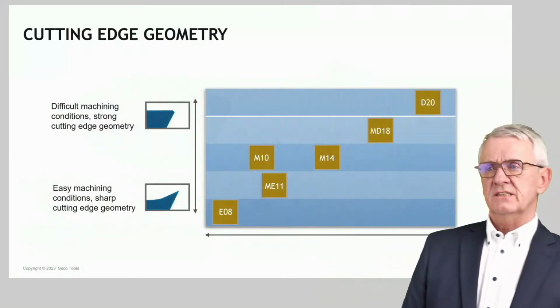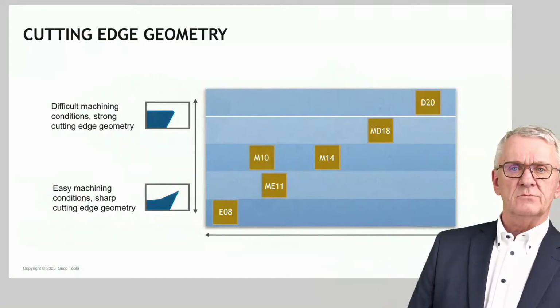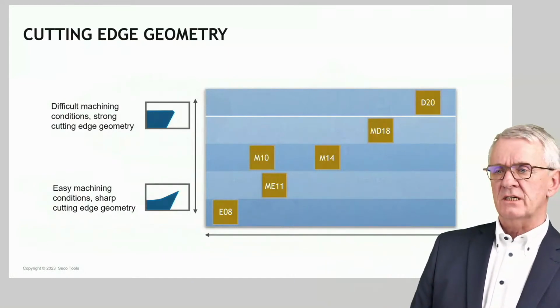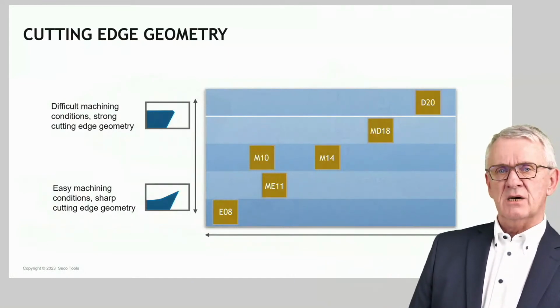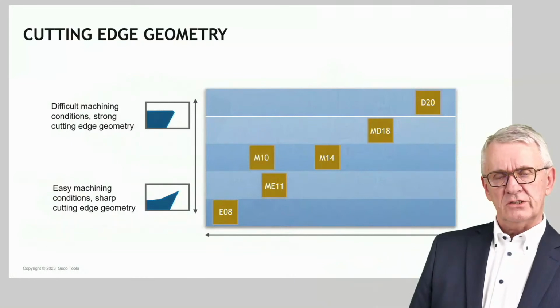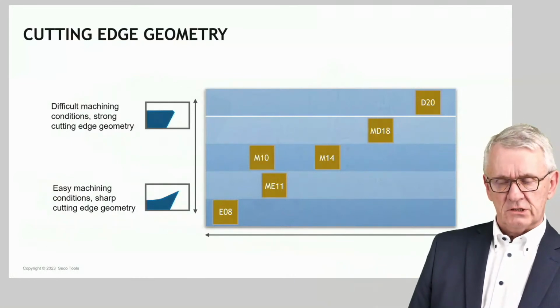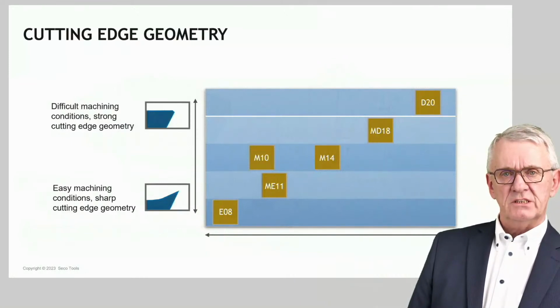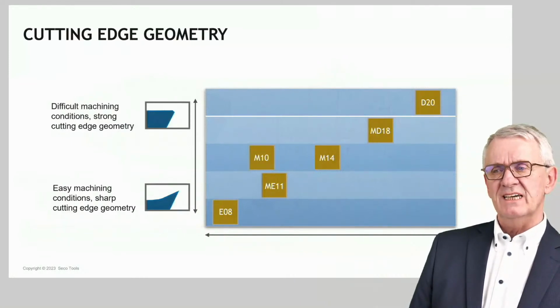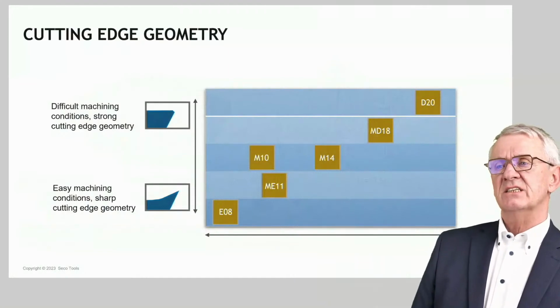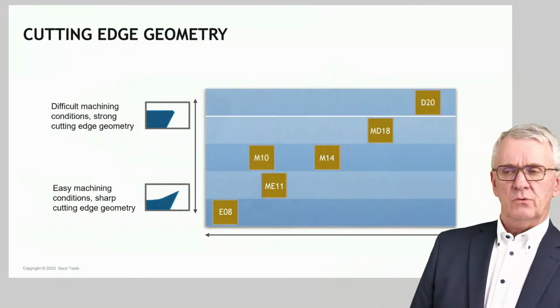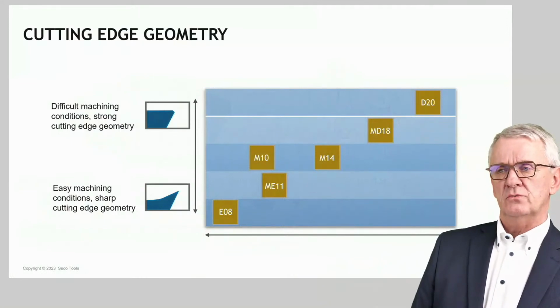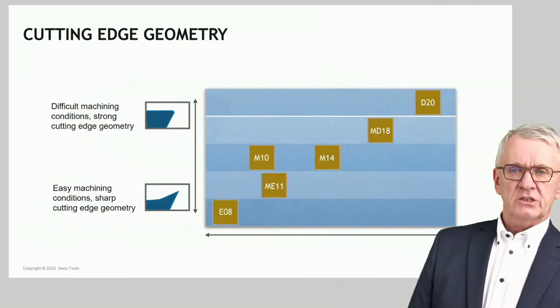And that is represented, for example, in diagrams like this, that for sure you have seen already. Here you see examples of milling cutter cutting edge geometries. And you see a number in each of these designations. The number indicates that this cutting edge, with a very typical geometry, whatever it is, should be used with a specific average chip thickness.